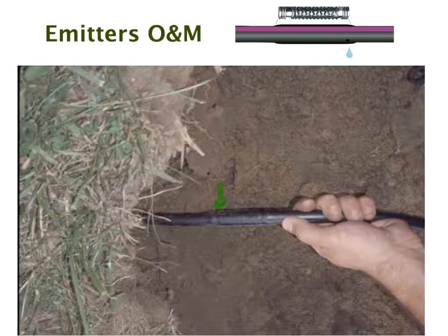The problem with VOD is the soil. In that particular case, we did have biological build-up in the soil because the soil couldn't handle the 1,000 milligrams per liter. The first year it was working fine, but in the second year we began to get slime in the soil. Which is inevitable. I think anybody that's worked with a conventional septic tank and drain field has an idea how this happens.